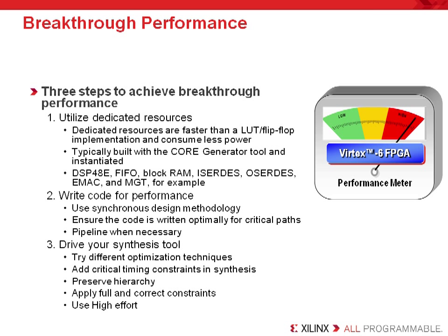To get optimum speed, device utilization, and minimal power, customers need to plan on targeting as much of the FPGA's dedicated hardware resources as possible. This means that users not only have to plan on instantiating the proper resources, but sometimes have to look for creative ways in which to use the dedicated resources. For example, most customers would think to build a FIFO with the block RAM, but most would not consider building a finite state machine with block RAM.